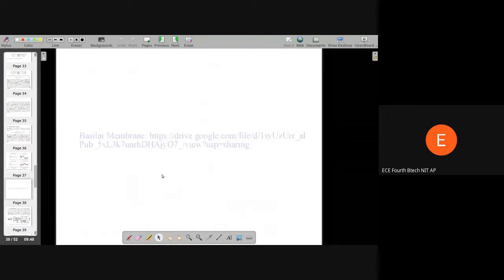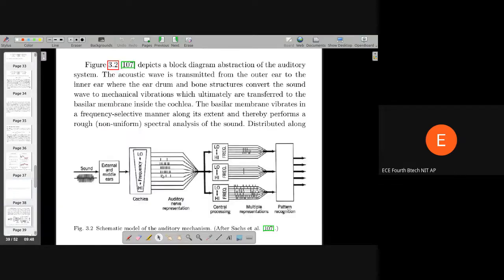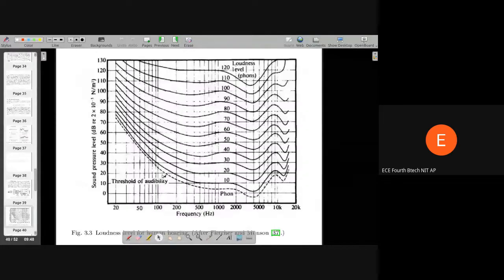Then, in our last week, we were mainly dedicated to the mel filter bank and MFCCs. The mel filter bank comes from how perception of speech occurs in the basilar membrane, which is like a frequency analyzer. We discussed in depth how perception of pitch is actually different from the perception of the fundamental frequency, even though we loosely equate them.